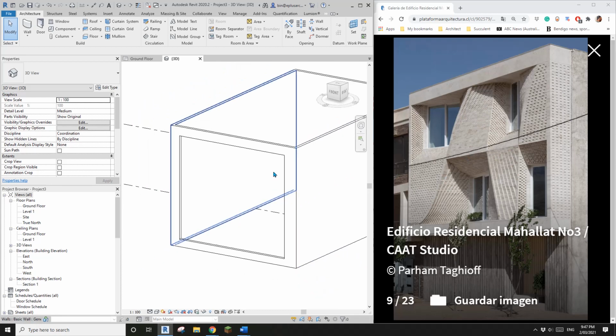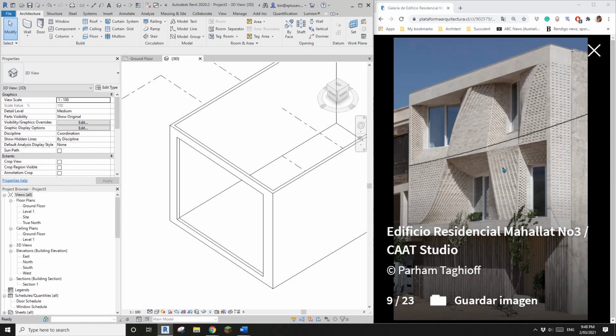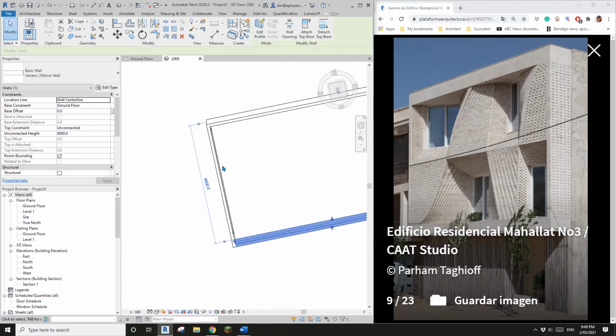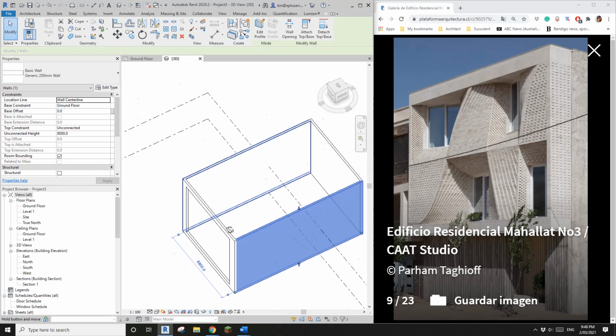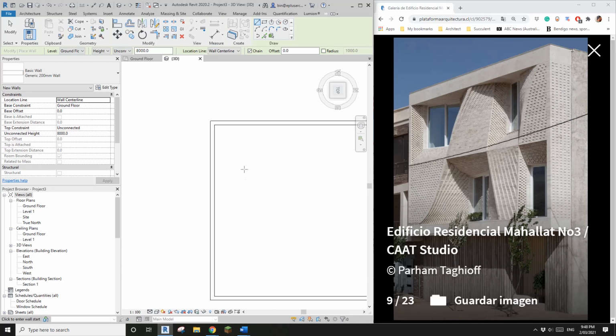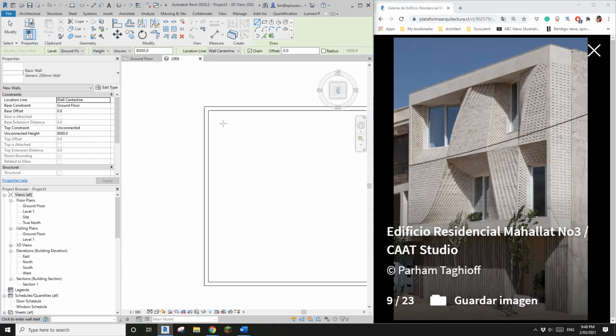Okay, but before that, I'm going to place some windows, because from this image we can see the windows are normal windows, just placed on an angle. So for example, this one's facing the right, this one's facing the left. So what I'm going to do is I'll place some wall behind this wall. Okay, so I'll go to the top view, and I'll just CS create some new wall. So for example, this one, I'll place a wall like this, and another wall something like this.